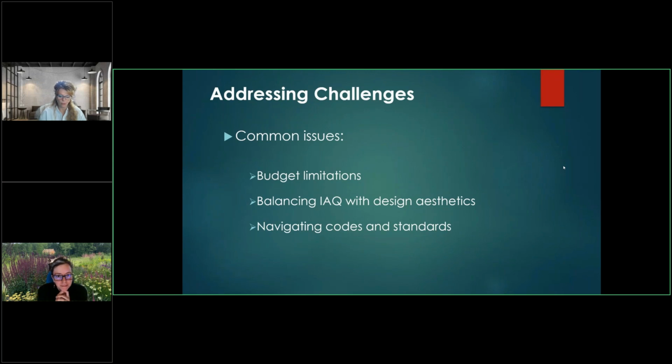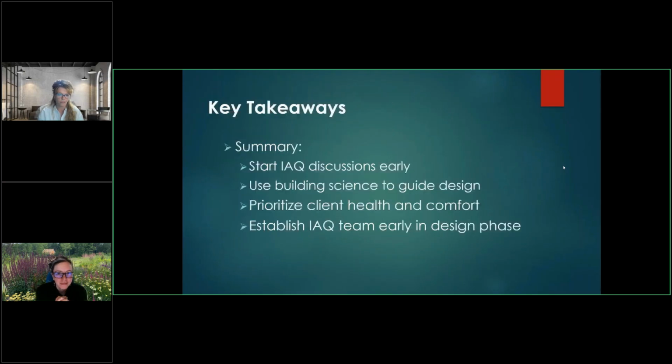I agree. That dew point one, believe me, I want a T-shirt that says "Do the dew" because to me it's all about dew point. But unfortunately, homeowners do not understand that. I do think there's more and more thermostats and controls out there that are running on dew point in the background, but what the homeowner sees is the RH. Hopefully our ventilation controls get more to dew point, but that's a whole other webinar, which I think we might do. This is 101, and getting into the next step of really diving deep into the weeds would be helpful.